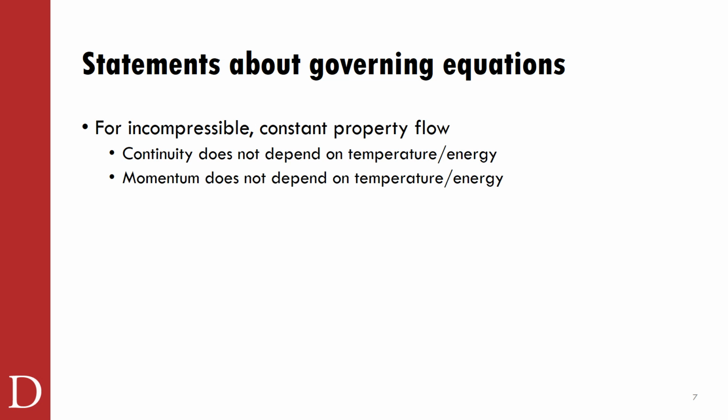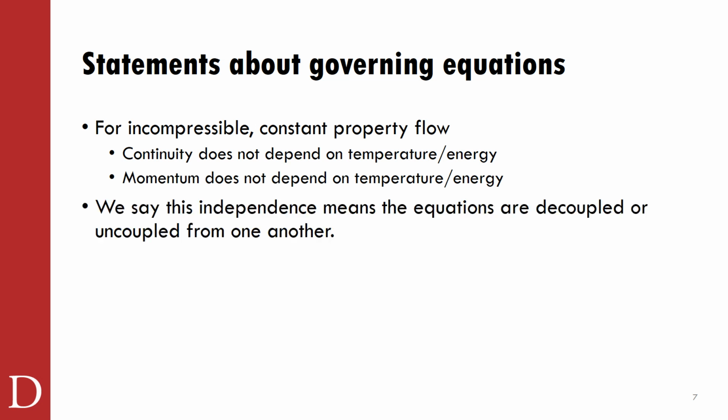Momentum, same thing, no temperatures in there. So those are uncoupled or decoupled from the energy equation. We can solve those directly. So that's good news. It makes it a little easier. We can choose which order we want to do those. We can solve continuity first, solve momentum first. They kind of relate to each other, but they don't relate back to temperature.